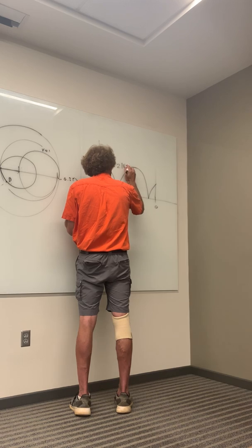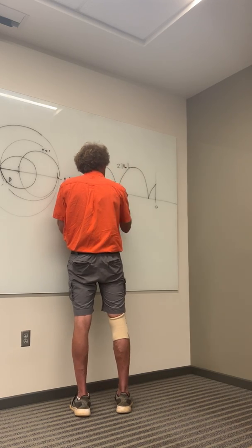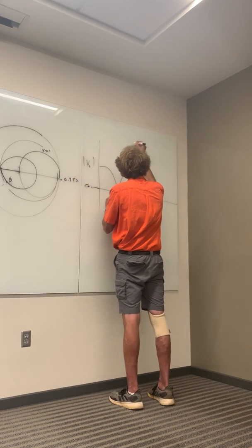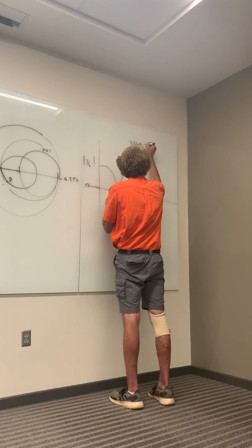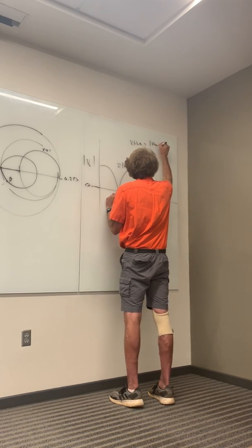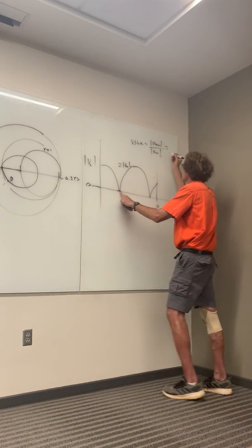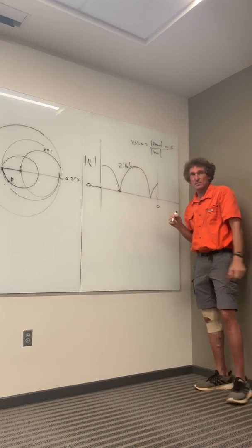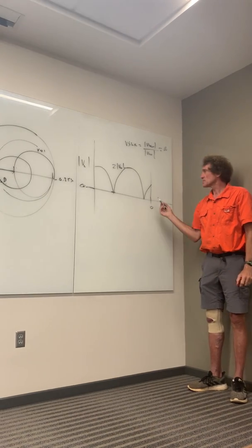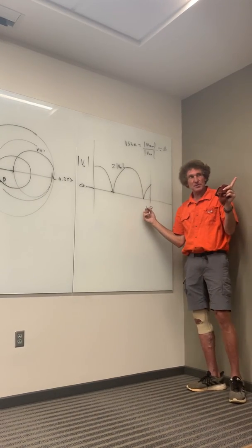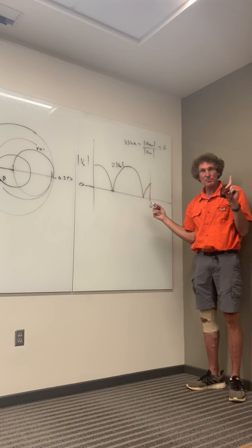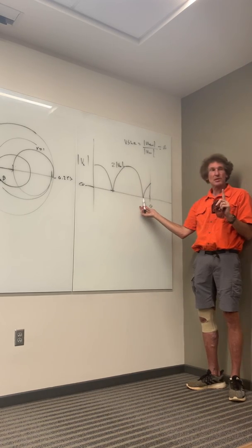naught, or Vn, call it Vn right here. But this is still 0, so the ratio, when you look at the VSWR, it's magnitude of V max over magnitude of V min. Well, since V min is 0, this is infinite. So that's right, you follow me? So this is what you're looking at when he has the short, but you'll notice something. That short circuit gives me 1 point that's very important. It shows me where the load is.